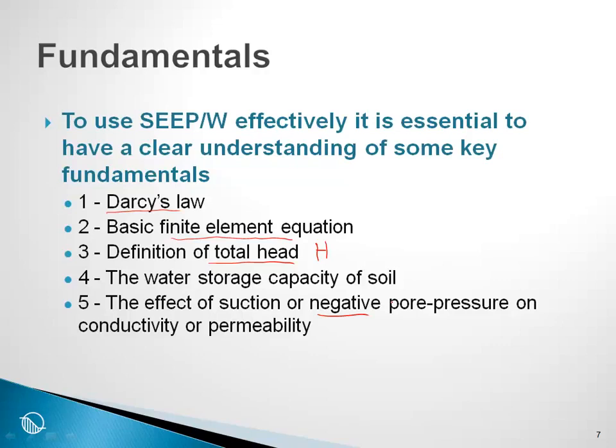What we will see is that when we move into unsaturated soil, the conductivity is no longer a constant, but the conductivity now becomes a function of the pore water pressure. So this is at the heart of a SEEP-W analysis if we want to consider both saturated and unsaturated flow.